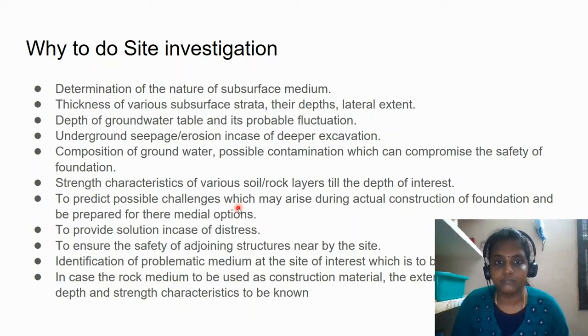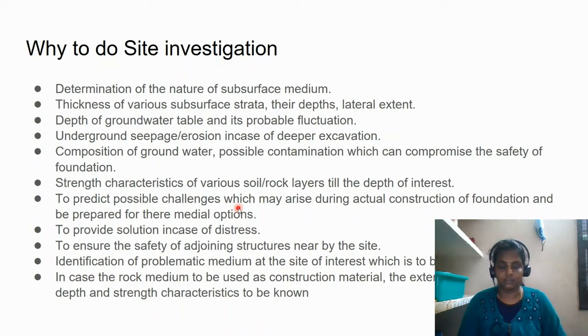From the bottom there could be artesian pressure from the site, and also there could be some utilities pipes. You might suddenly damage a gas pipeline or a petrol line, utility line mains that go through your site, and you don't know. So we have to be prepared. What could be the possible issues that may come?